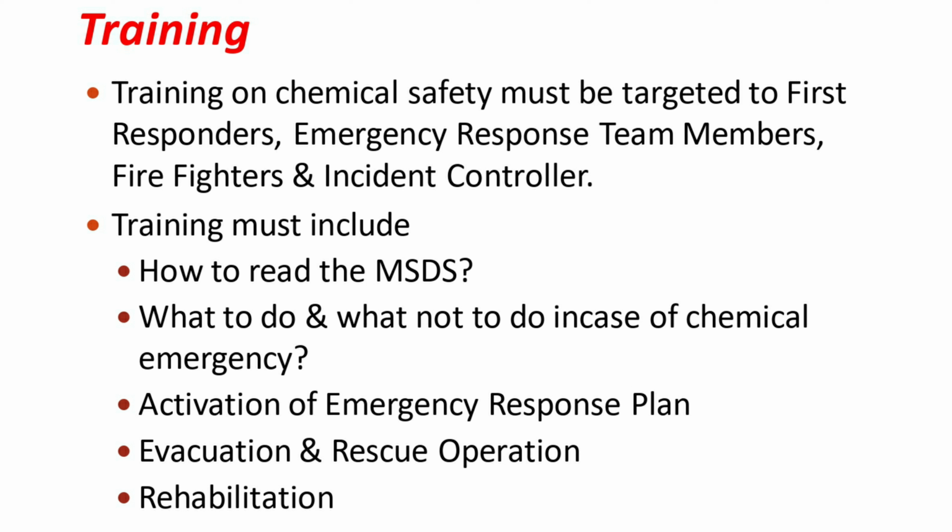Training. Training on chemical safety must be targeted to first responders, emergency response team members, firefighters, and incident controller. Training must include how to read the MSDS, what to do, and what not to do in case of chemical emergency. Activation of emergency response plan. Evacuation and rescue operation. Rehabilitation.